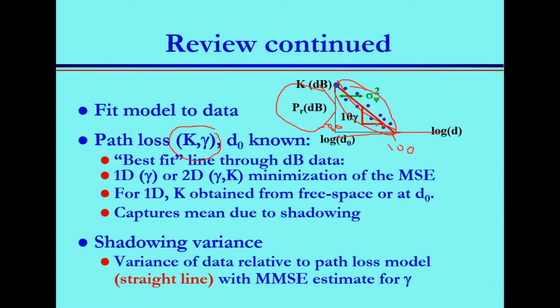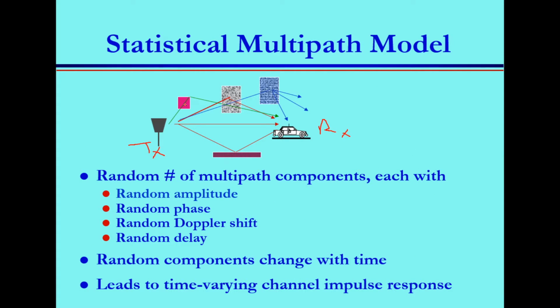Now, the statistical multipath model, the new type of channel impairment that you might encounter when you send your signal over the air. So you have the transmitter here, transmitting your signal through the air wirelessly, and you have the receiver, RX. Your signal hits this building and gets reflected. Not one path, multiple paths, because it's an electromagnetic signal.